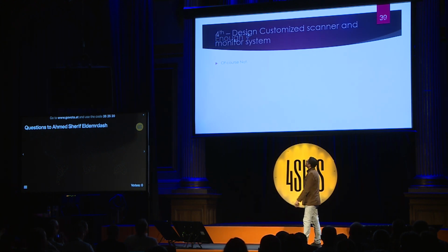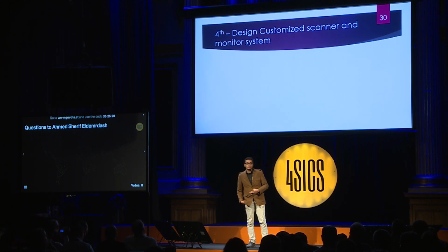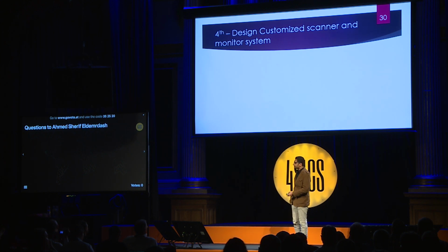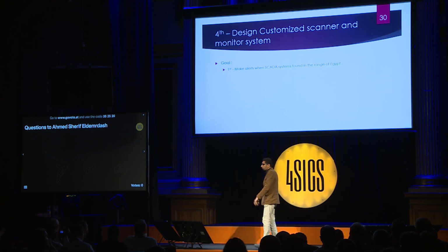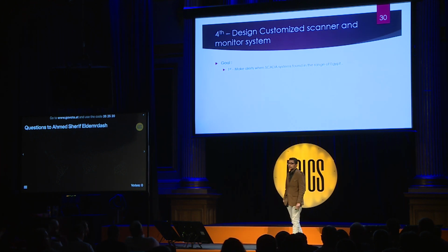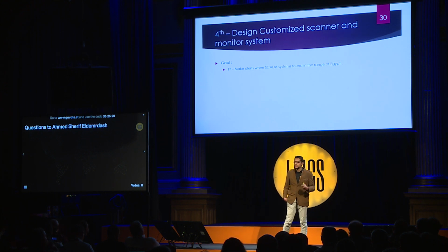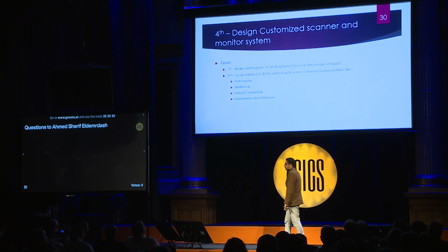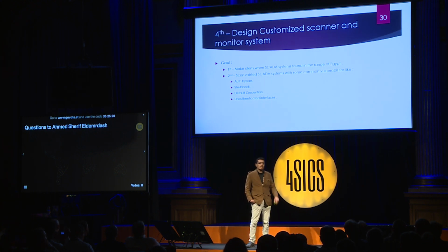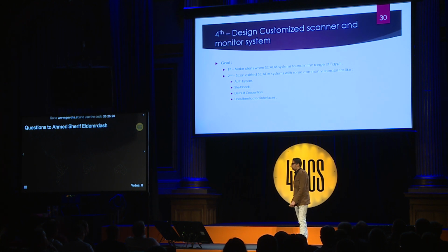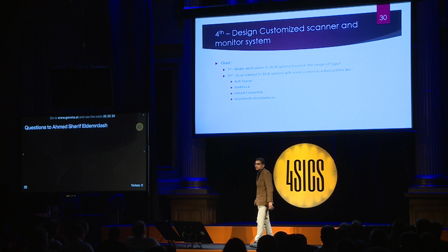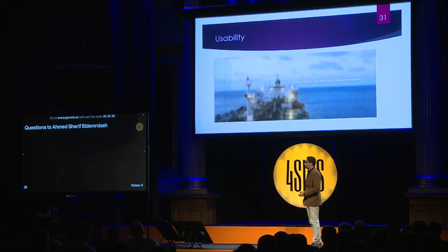So I designed my customized scanner to monitor the whole range of Egypt by making alerts for online systems. There were 2 goals for this scanner. The first is identifying interconnected SCADA systems, so that the scanner can make an alert for us and we can contact the organization and tell them, hey, you have an interconnected SCADA system and it's very critical, so we have to take it off. The second goal is identifying existing SCADA systems with common vulnerabilities, which were found on honeypots, such as common web attacks like authentication bypass, unauthenticated interfaces, web interfaces for SCADA systems running default credentials. So I will pass this.